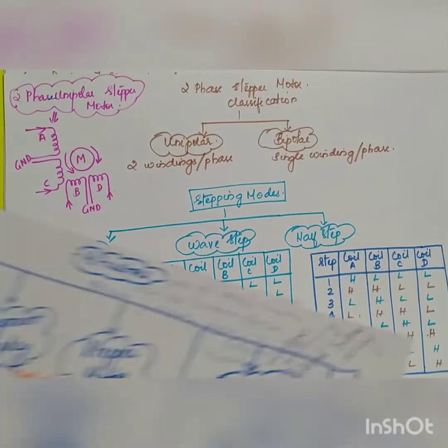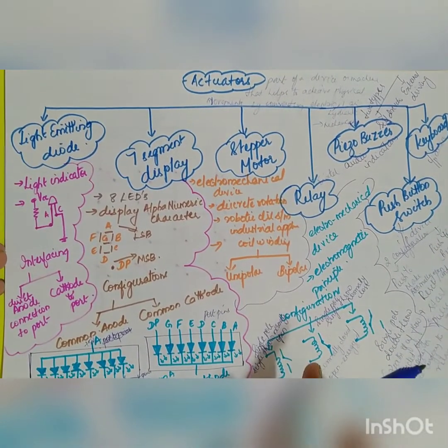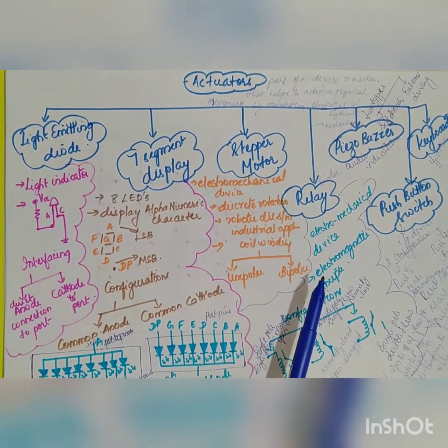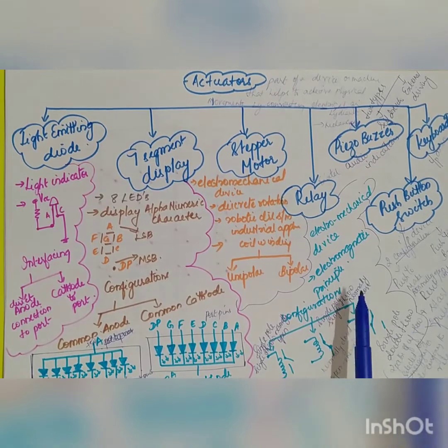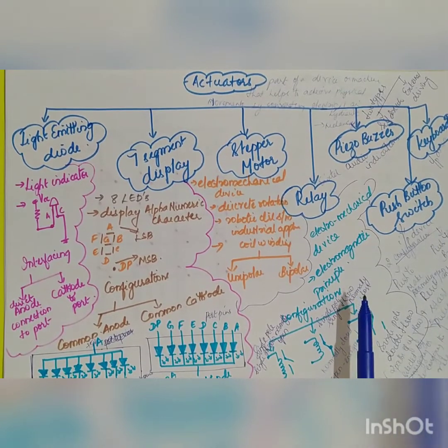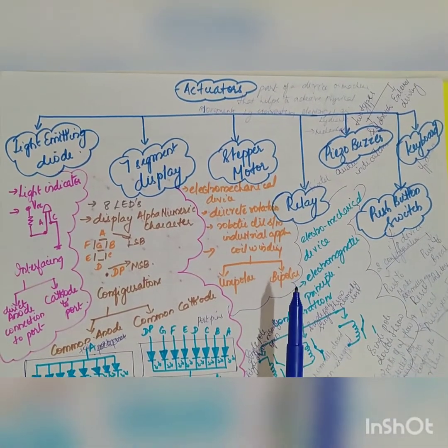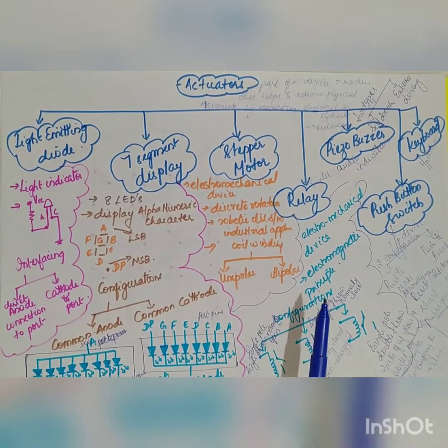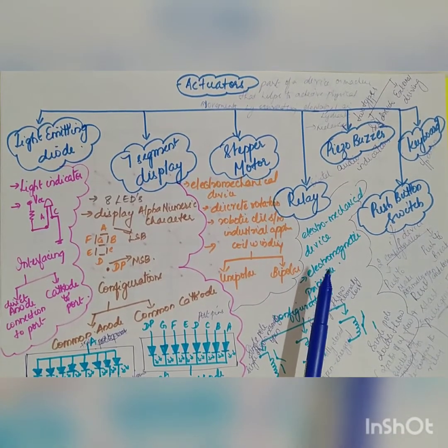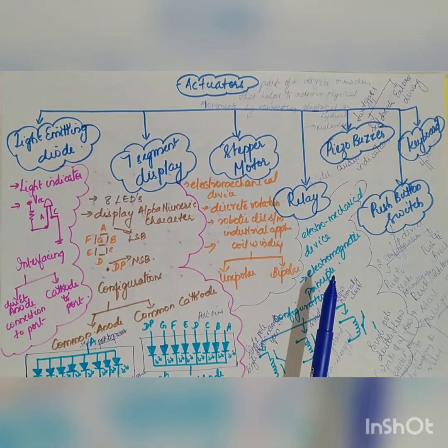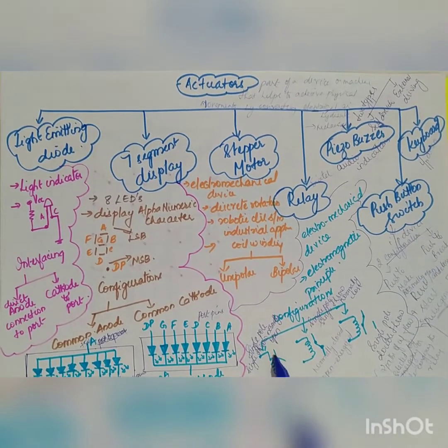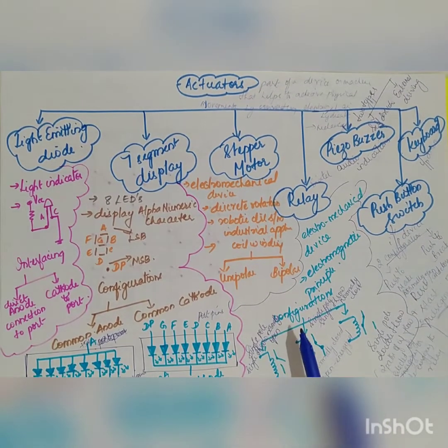The next topic is called the relay. So what is meant by a relay? A relay is also an electromechanical device. It works on the electromagnetic principle. In embedded applications, it acts as a dynamic path selector for signals and power. So it contains a relay coil, made up of insulated wire on a metal core, and a metal armature with one or more contacts.